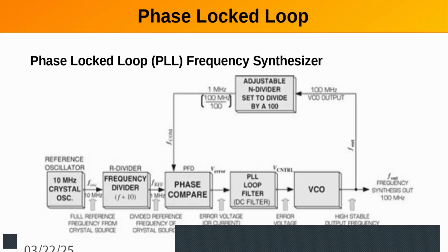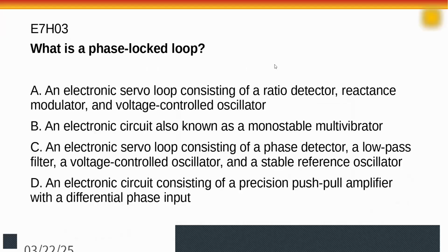So it's not really locking just the frequency, it locks the phase, not only the frequency, but the phase. So you can have a frequency generator that is the right frequency, but it could have phase shift in it. Not with that when it's locked. For Apollo, the receivers for the telemetry were phase locked and would actually lock on the frequency.